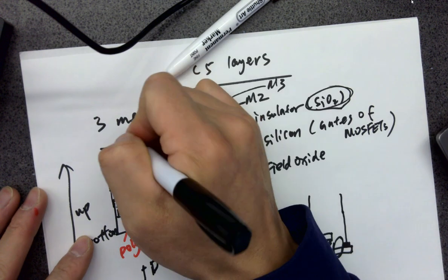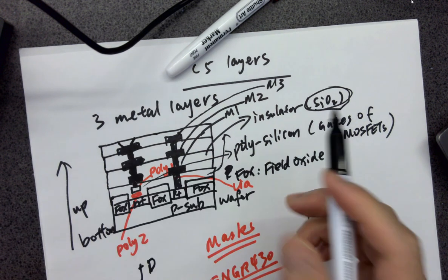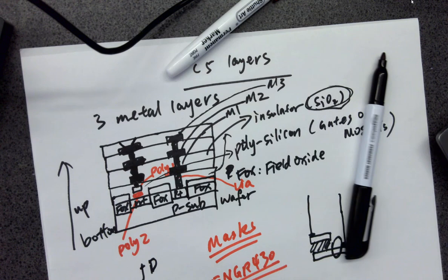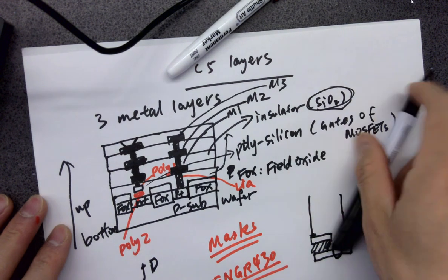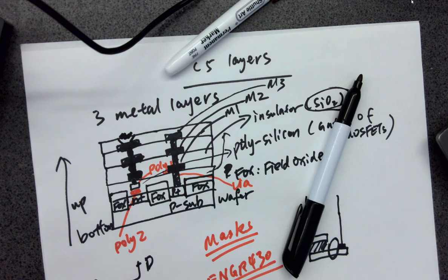So this top silicon dioxide can be opened up by a chemical, right? So it's gonna open up on the top and eventually expose this metal 3. So metal strip exposed. And they can use the wire bonder. It's a $20,000 machine in my lab, okay? And it's functioning, which is important.